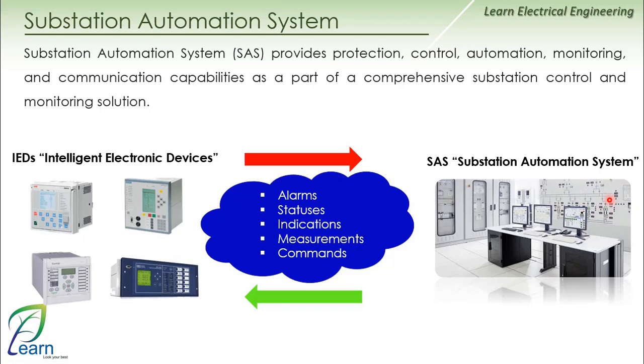It illustrates all the components present in the bay, from disconnectors or isolator switches, earthing switches, and it would tell you where your feeder is going or where your bay is going. For example, is it going to an overhead line, underground cable, transformer, static var compensator, or whatever? The important thing is that it would show you the single line diagram specific to your bay.